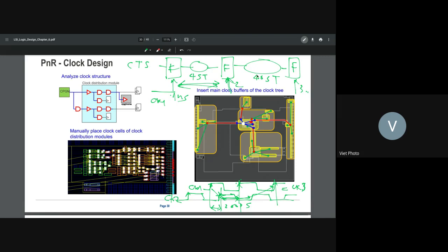So that's why it's not always that the clock would be balanced. A balance is a good thing, but in general this is only for the critical part, right? For the critical part, usually we are happy if the clock is balanced, that's the best thing to happen first, and later on we do the step where we skew the clock to have a different arrangement.